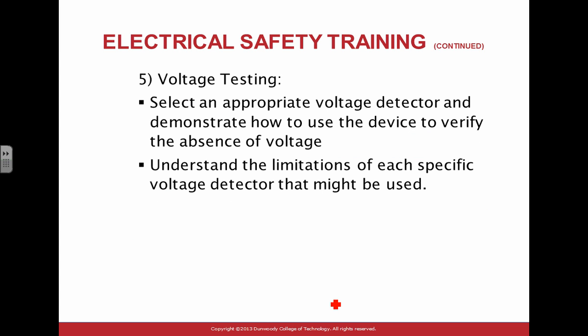So that's it, and then voltage testing. Now we know how to do it. You have to test voltages, like we talked about with the meters. Select an appropriate voltage detector and demonstrate how to use the devices to verify the absence of voltages.